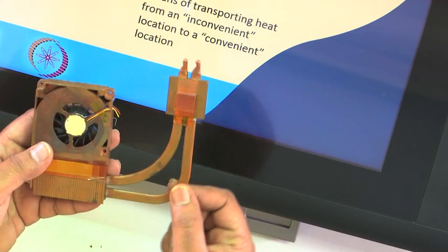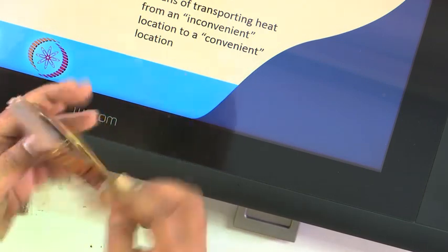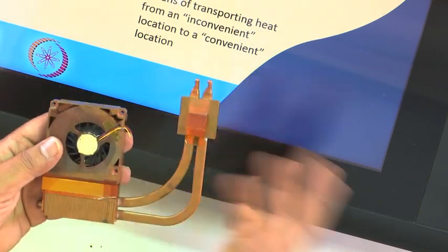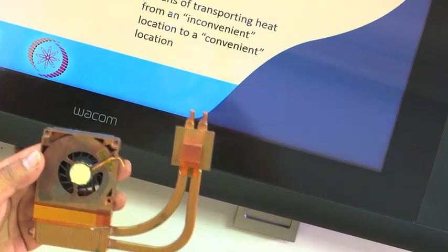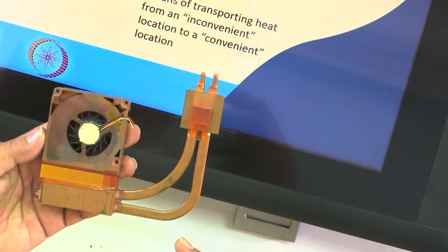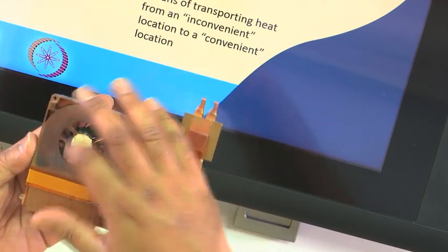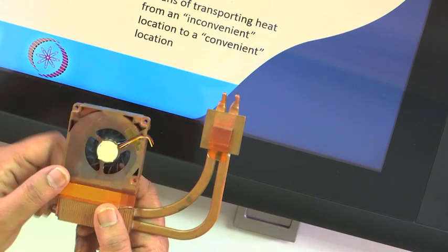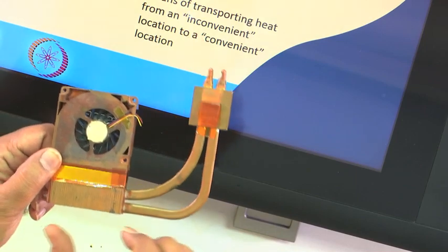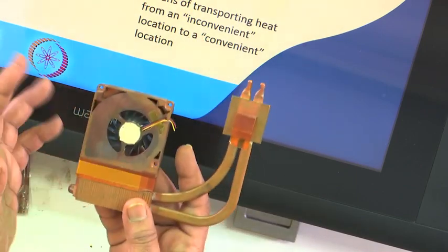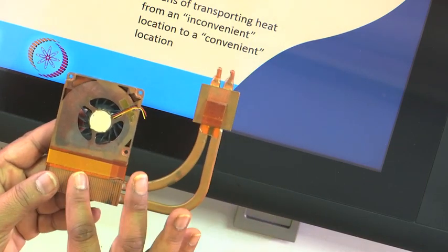So, therefore, whether the heat pipe is going to have a bend or whether it will be straight or whether it will have two bends, whether there will be two heat pipes, whether it will go on the fan casing like this, these are pretty non-standard. These vary from one model to another, but the basic principle of a heat pipe heat sink arrangement is the same. So, this fan blows air. As it is powered on, the fan blows air through this heat sink, and that is how the heat is extracted from here, transported to here and rejected.